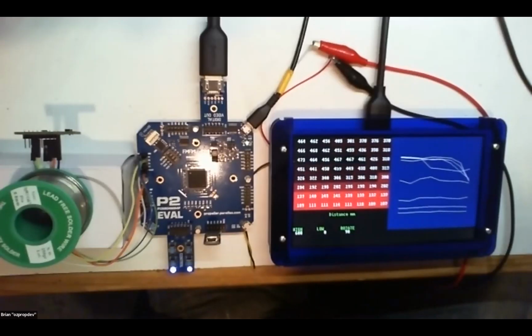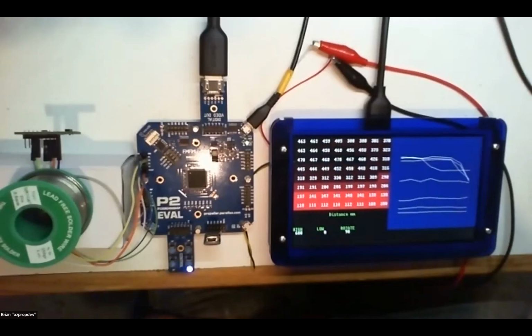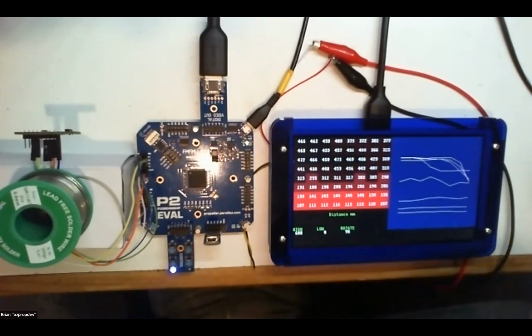Hey, Brian. Yeah, so this thing actually returns 64 measurements per cycle, that's right, and you can have it be one-dimensional 16, or you can have it two-dimensional 4x4. It's still two-dimensional 4x4, it's just to get the frame rate up. They obviously just drop off their sampling. There's an MCU on board that when you first initialize the thing, it loads about 85K of firmware into it, and it's doing all the hard work. And yeah, it's just basically streaming out the 64 measurements.